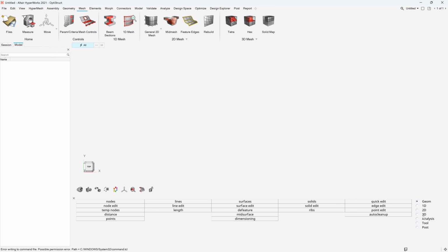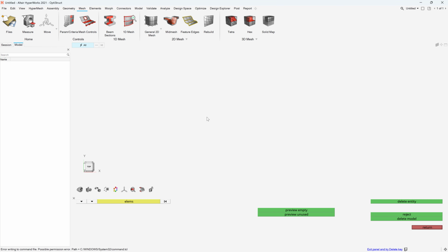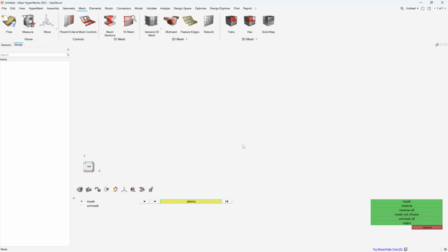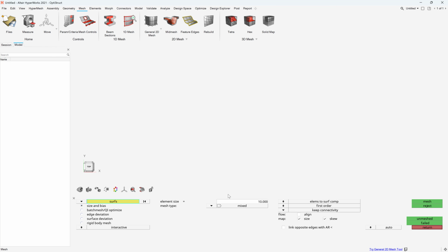They already did actually. They already provide a ribbon based icon, user understandable icon, as well as they provide the traditional options. Every shortcut key, if you press the F2 button from the keyboard, that will go to the delete. If you press F5, that goes to the mask. If you go to F12, that goes to the automesh panel. Everything was there. So the new user can understand from the top ribbons, and the old user can easily use the previous shortcut keys, previous traditional method. But why did they ignore, why did they eliminate such kind of traditional method options?